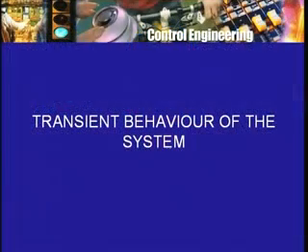Before we take a look at the other schemes of feedback, namely integral control, derivative control, and even more general types of feedback control, we should look at the transient response or the transient behavior of our speed control system. Why? Because, as I said earlier, in the feedback scheme that we had talked about, namely proportional control, it looked as if you could reduce the steady state error when disturbances take place to any arbitrarily small amount by increasing the gain Ka sufficiently.